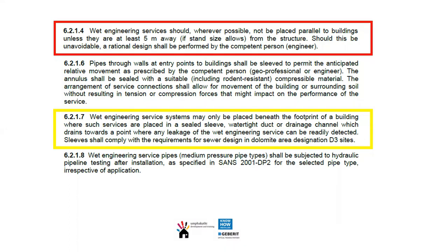And time and again, we see that the outer sleeve or the inner pipe always gives a problem because they are not done properly. You know, the competent installer is the real challenge. Having all of your junctions underneath the ground, underneath the footprint of a building, like in a shopping center, you've got to put those into a chamber to make sure that they are actually properly sealed. So this goes away from the norms of a normal manhole, in that you don't have channels and junctions, you have a watertight box and your junctions are then housed in that.